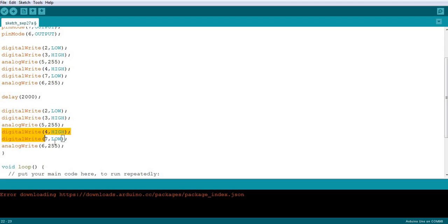And these commands are moving the right wheel forward, but we don't want the right wheel forward now. We want the right wheel backward, which means we should change the direction. And this is what is going to decide direction. It was high-low, now we made low-high. That will ensure that the right motor moves anti-clockwise, which is backwards for the right motor. So the right motor is moving backwards, the left motor is moving forward. That will ensure that it takes a hard right turn.